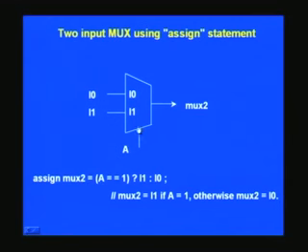And here you have a select signal, and this select signal must be put first, and within brackets if you like. This is not the only way of writing. In fact, you can dispense with all this, including the brackets, and just have plain A, and it will still work. Or if you want, designers normally prefer putting 1'b0 or 1'b1 like that, because that gives an indication of how many bits of precision this signal has. Here of course it does not arise, and it need not be necessarily this alone, we can have even a multi-bit thing as an assignment here.